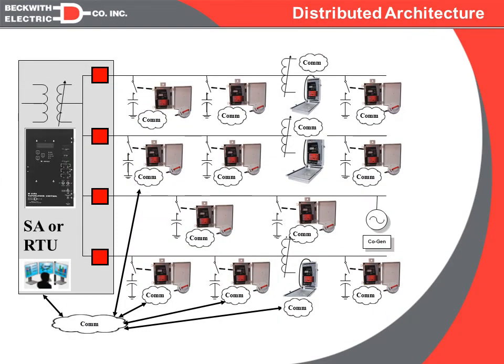So what we have done is we've replaced our SCADA system up here, and we moved it down to within the substation fence. And the IVVC application is now going to run either on a substation automation system or your RTU. And that system will be the one polling all the controls and determining when to operate which of them. So all we've done is we've taken one centralized system and broken it down into many smaller decentralized systems.